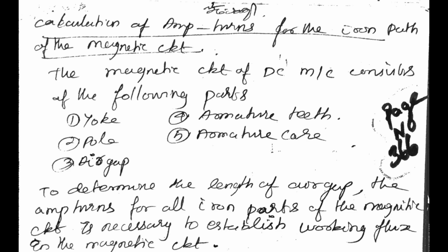Good morning to all. Electrical machine design. Topic: design of commutator brushes. Problem: obtain suitable dimensions for the commutator and brushes of a 1000 kilowatt, 500 volt DC generator having the following data: outside diameter of armature 170 cm, number of poles 12, number of armature coils 540, RPM 500.